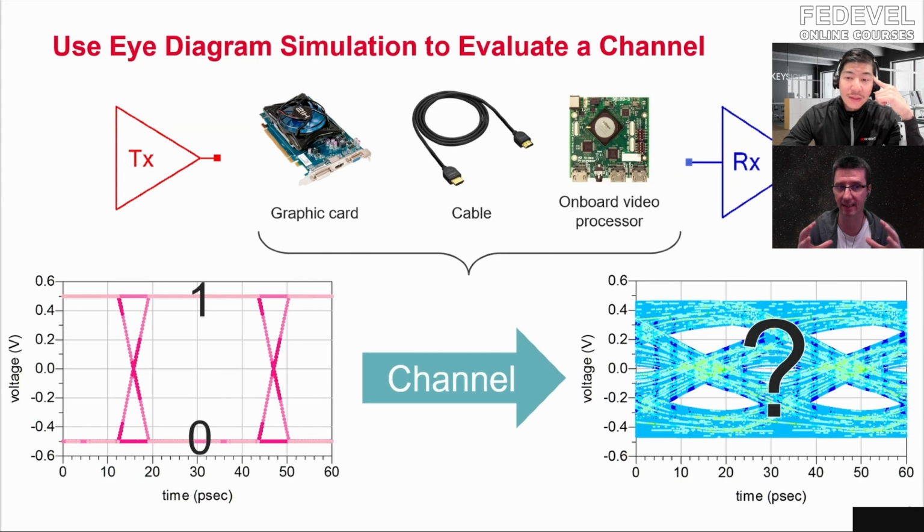That's why this eye diagram is so important: we are not looking only at one signal, we are looking at all the kinds of signals, how they actually look in a transmission line, correct? Yeah, exactly. It's the overlapping part that's most important. You're taking a very long signal and combining it into one single picture.